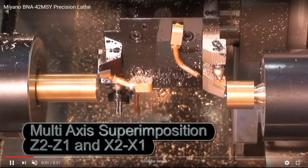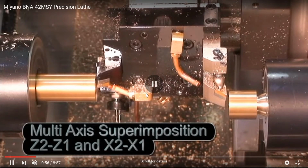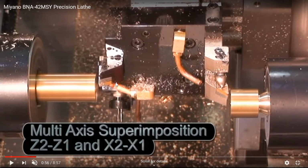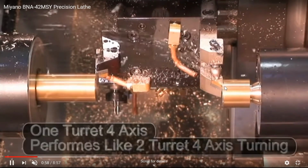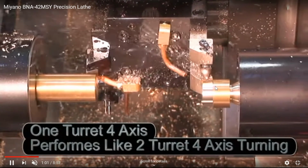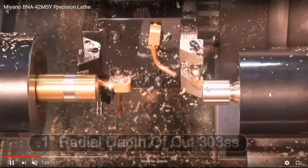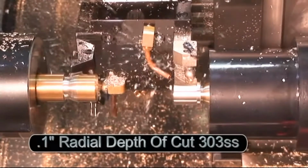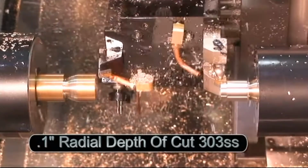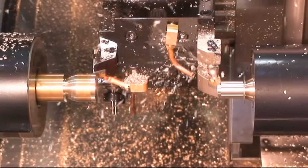Basically, what you will be able to see is that 2 parts are machined together, where the Z1 axis is the main axis and Z2 and X2 are following the revolver. As you can see, even in the rapids, the part follows the tooltip all the time. So in this webinar, I'll try to demonstrate that our end goal is to run this mode in SolidCam, and also show you how to implement that inside the post-processor.